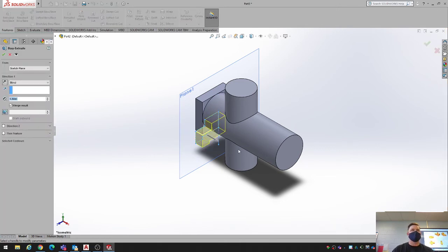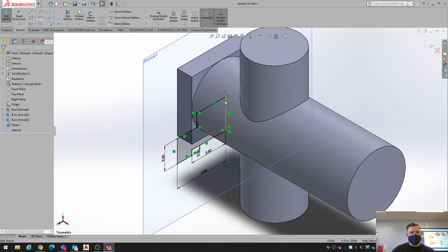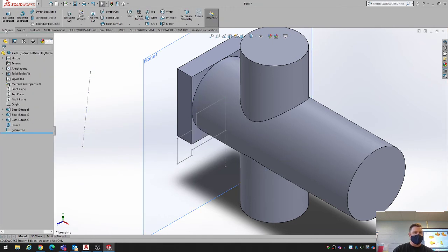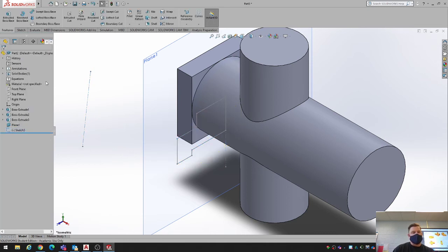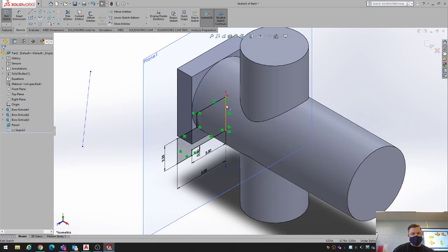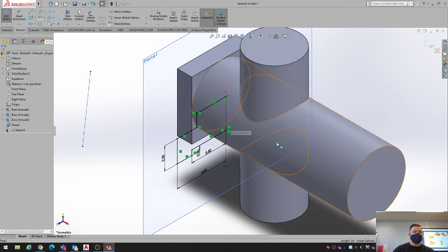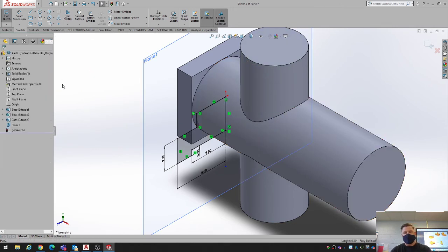The center line doesn't get extruded. As long as you, like, if I go in here, actually I drew over the center line. So yeah, I am, technically. But if I just draw a center line like this, and I just have it floating out here, and you go to extrude it, it ignores that center line. No, that's why I created two lines. See, the center line is underneath it. If I delete this line, the center line is underneath. If I just left it like that, it wouldn't work. I had to create 2 lines going there and there. Okay? Anyway,